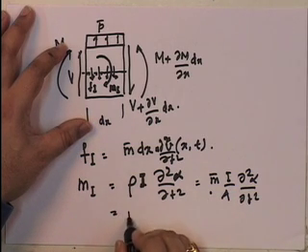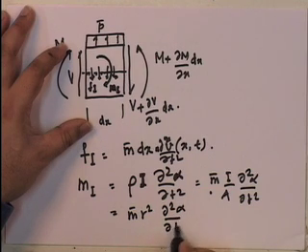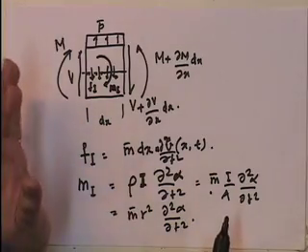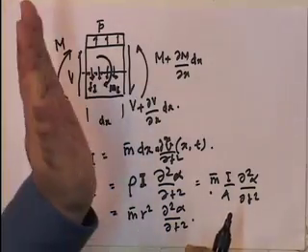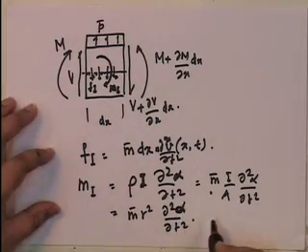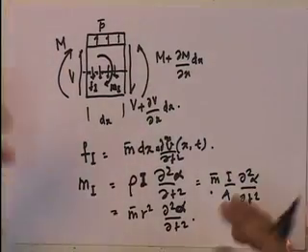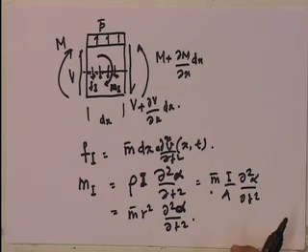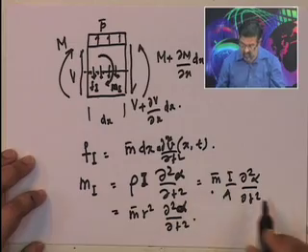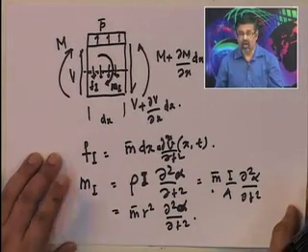So, this is equal to m bar r squared del squared alpha by del t squared, where alpha is the rotation of the cross section. So, therefore, this is the total rotation, because ultimately the mass only sees the rotation. It does not see how much the neutral axis moves by, etc. So, these are your F I and m I.